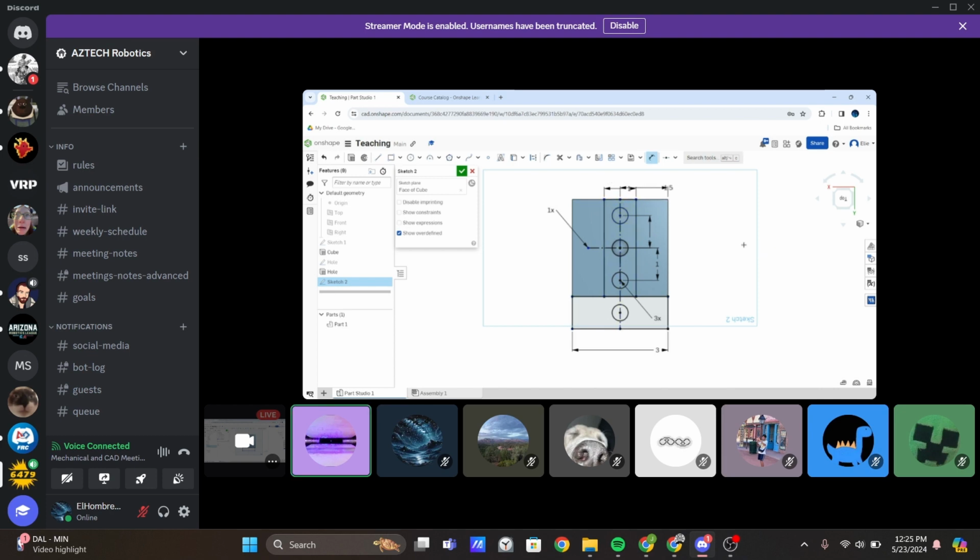Sometimes when it all turns red, it means that the sketch geometry doesn't work out if you try to add a relation. That can happen a lot if you've accidentally added a relation that you didn't mean to. Sometimes you've got to go back and delete them and just guess and check and figure out what's causing that. It can be a bit of a pain sometimes.